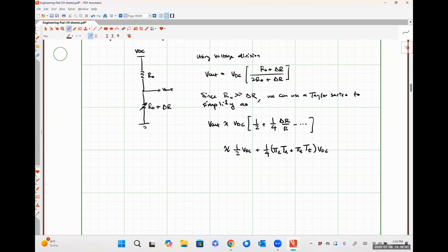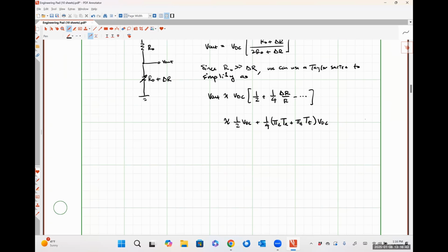So we still have a DC term, and we've got our signal that is dependent on temperature, but we don't really have to worry about the temperature change in our resistivity coefficient here, because both the reference resistor and our sensing piezo resistor will experience the exact same change. So those guys wash each other out. So we only see the effects of piezo resistance in this particular case.